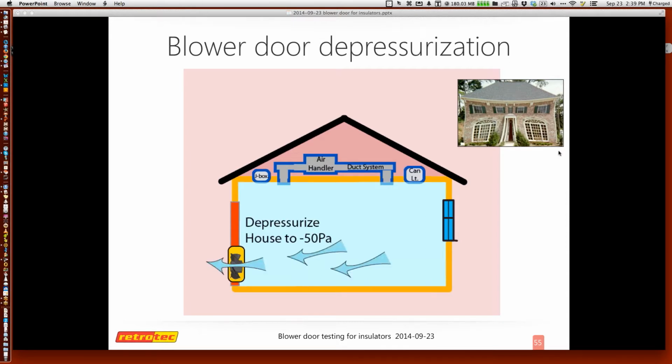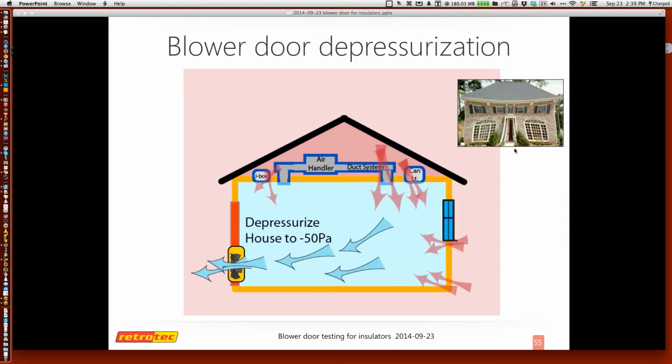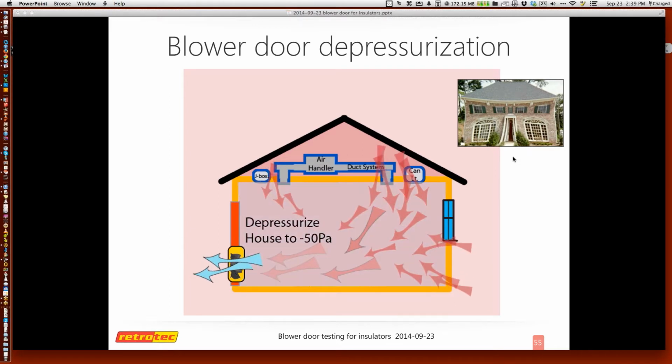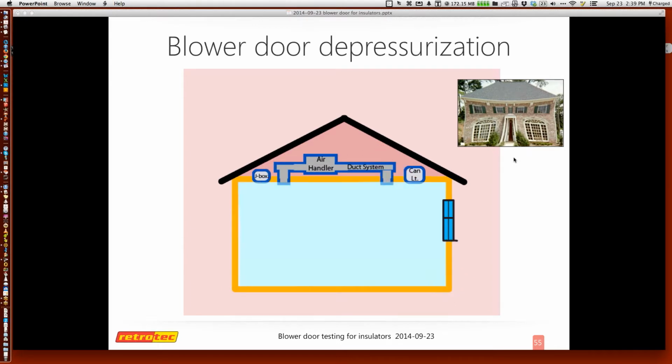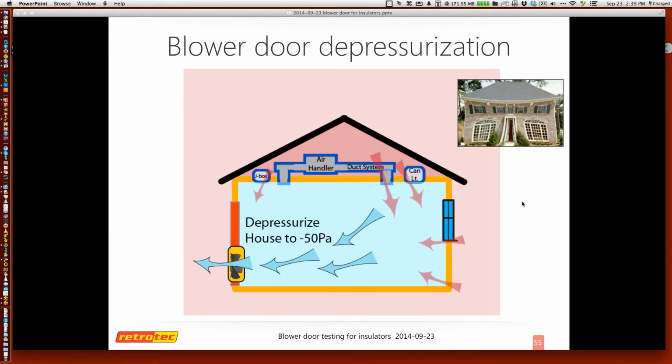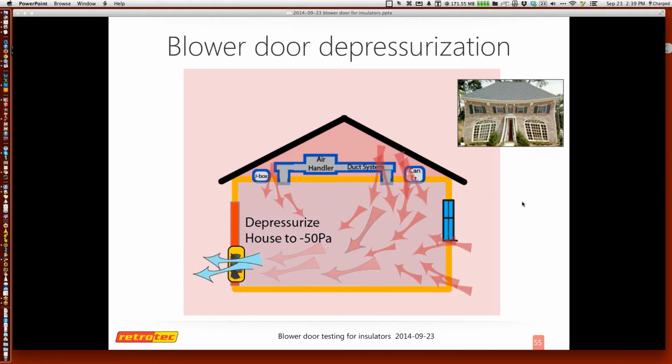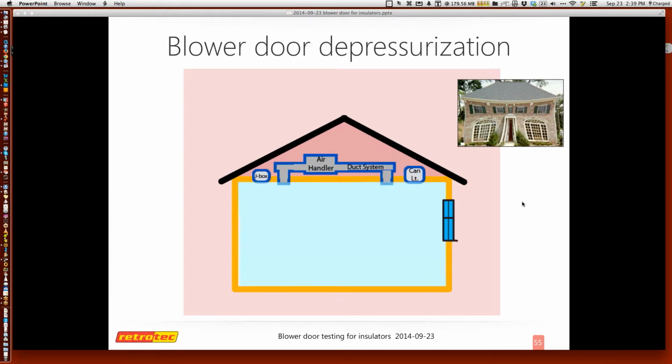They show up as openings underneath the sinks. And all those should have been sealed actually at the top or bottom plates. It doesn't help to actually seal the receptacle. You really want to go to where the leakage actually is. And sometimes it's difficult to get to after the fact. So if you're testing and there's drywall up completely and you're failing, you're going to have some challenges as to how to actually resolve this condition.